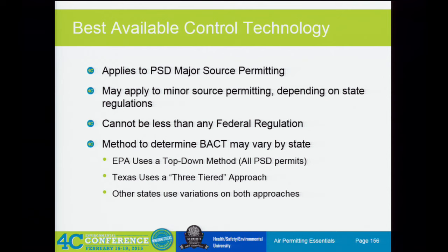It cannot be less stringent than any federal regulation. So if there's a federal regulation for your emission source that establishes an emission limit, that is the highest emission rate that can be used to determine what BACT is.